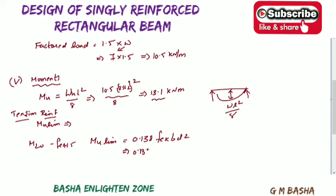So 0.138, and fck for M20 grade is 20, and b, the width of the support, is given as 200, and d is the effective depth, that is 160 whole square. Each and every value you know. If you simplify, you will get 14.13 kilonewton meter.